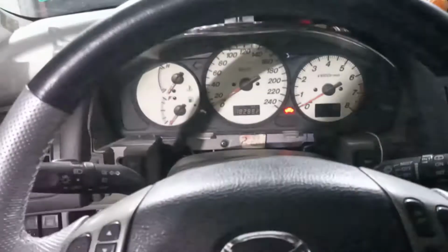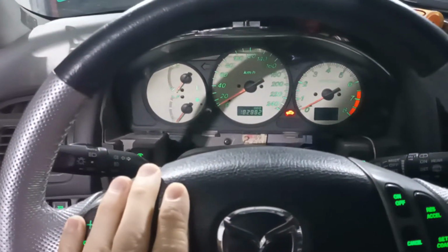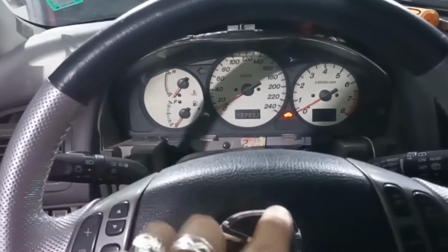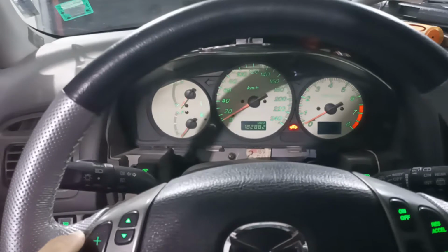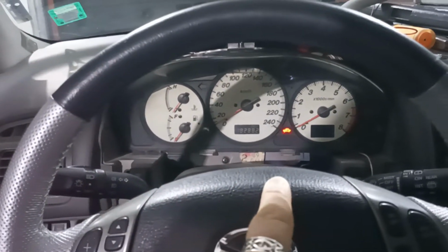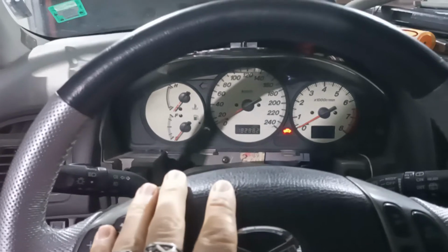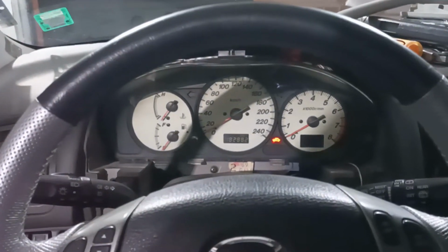1, 2, 3. And the car now responds with 1 beep, which means get out of the car to look at the outputs. The outputs show the TNS, then the headlights, and then the daytime running lights. Then you go back into the car, and it beeps 1 long because it's version 1. If there's a minor one, it will be short ones also. 1 long to tell you it's parameter 1. And short, long, short, that is a pattern for all parameters, which means the value hasn't changed from the default.